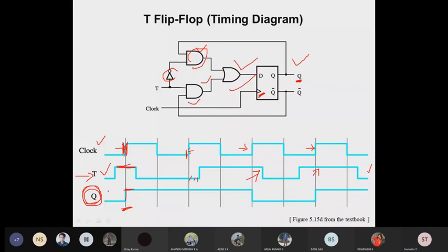Likewise, for the immediate pulse, for the initial stage, it will be reflected immediately. That is, the input value and the clock have been synced, so obviously you will receive the same output value. But after some time, since the internal circuitry of the T flip-flop consists of more circuits, it has some propagation delay. Everywhere it has some propagation delay. That delay will reflect on the output value.